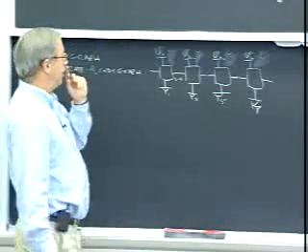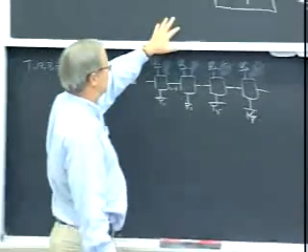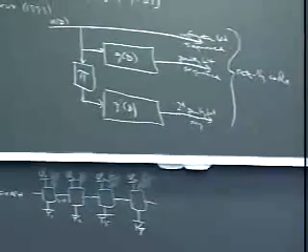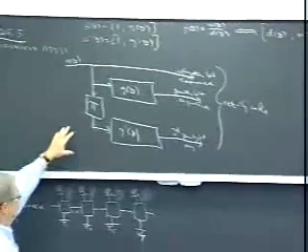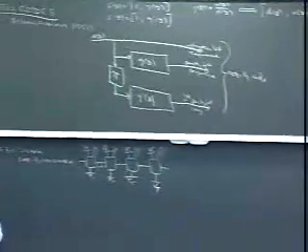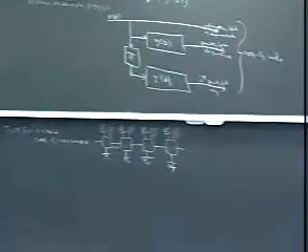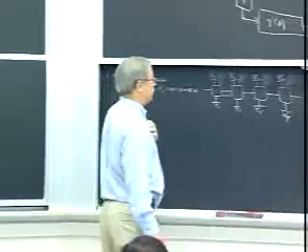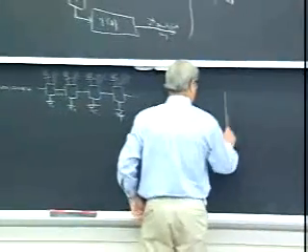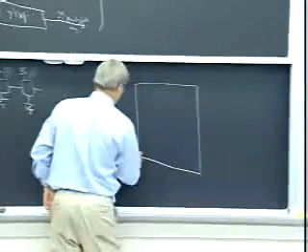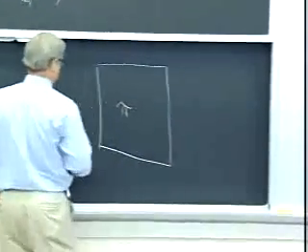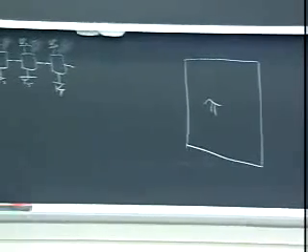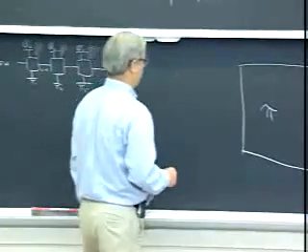Now up here, I really have 2 of these codes, possibly identical. And what's the connection between them? The connection between them is that they have the same information bits in some random order, some pseudo-random interleaved order. So I draw a graph of that. Again, I'm going to focus on the interleaver, make it nice and big now. There's always going to be a big interleaver in the center of all our charts. This is always the random-like element.